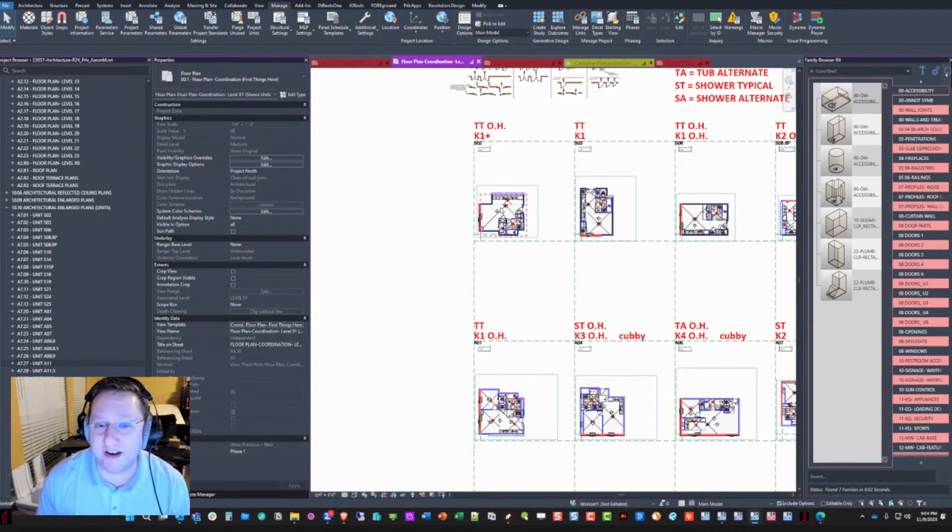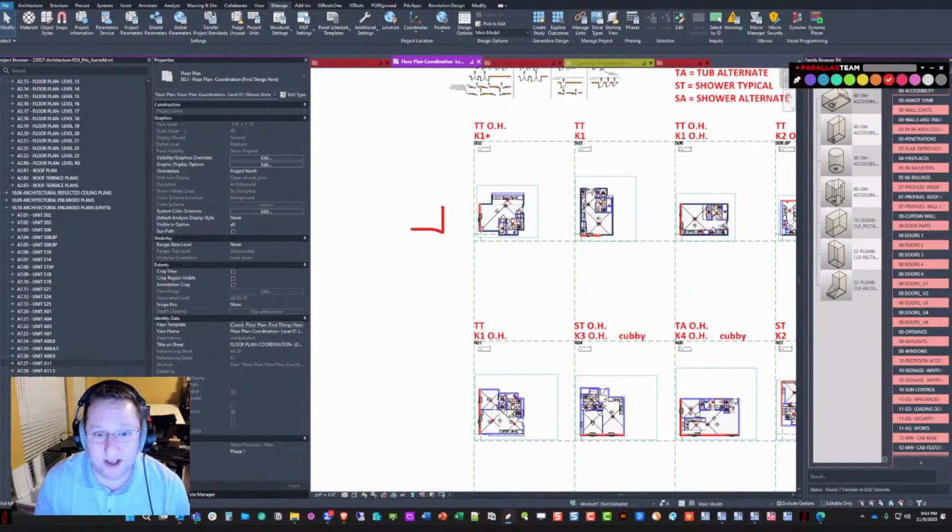If you have that, what a lot of our clients will actually do, and I love this approach, is they'll have units that are grouped, and then around the building, they'll actually have exterior facade pieces that are groups as well. Now that works really well because if unit S1 always has this particular facade at the corner, then you just take that facade group and you drop it in context. Copy the instance there, right? Yeah, and it does the exact same thing.